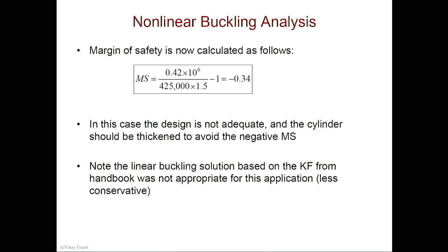For example, you're looking at a problem that has a cylinder with a window. I don't know if there is a solution out there or an experiment out there that'll be representative of that. So therefore, you yourself are going to try to determine the buckling load for that scenario using a nonlinear analysis, using RIKS, that uses imperfections from a linear buckling solution. So it's a two-step process. The first analysis is a linear buckling analysis. The second analysis is a nonlinear RIKS analysis. And in that nonlinear analysis, you're incorporating the imperfections that come from the mode shapes from the linear buckling run. You can read them in.